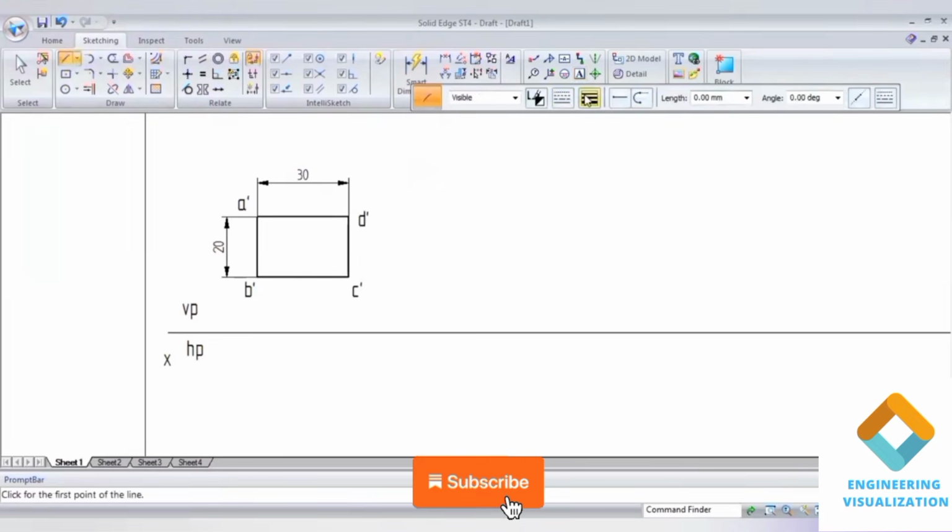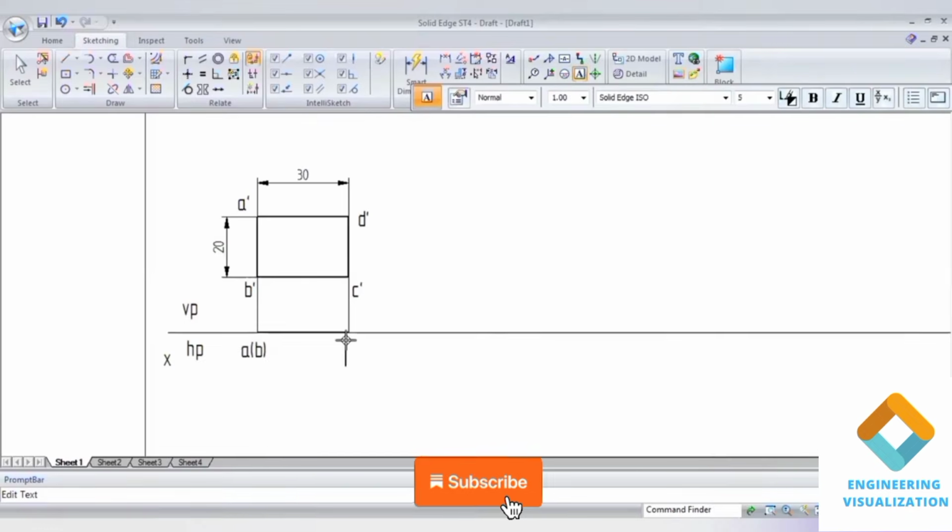Okay, write down the notations and draw the projection lines to complete the top view. So here B and C are not visible. That's why B and C are written within brackets.